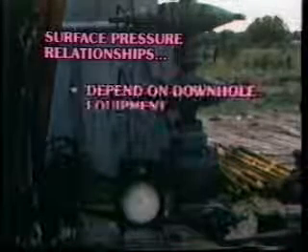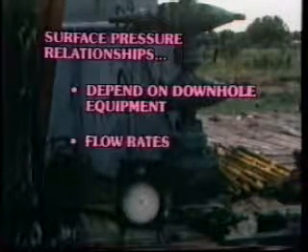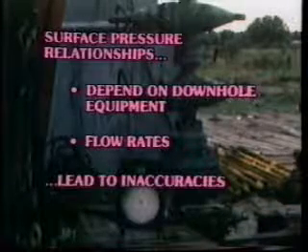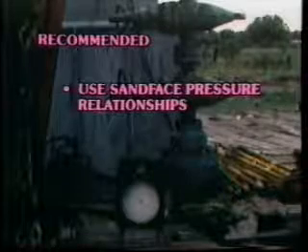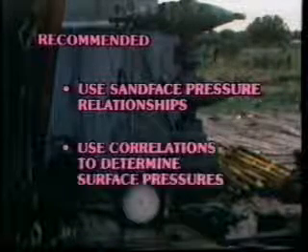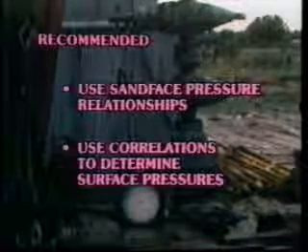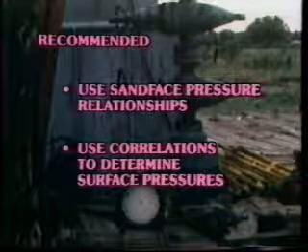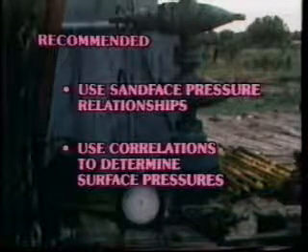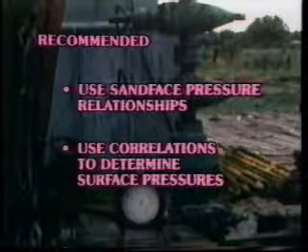However, because the difference in pressure between the surface and sand face depends on downhole equipment and flow rates, a relationship founded on surface pressures will not be constant throughout the life of the well. It is recommended, especially at pressures above 2,000 psia, that the fundamental relationship for the deliverability of a gas well be based on sand face pressures, and that appropriate correlations, usually available in existing computer programs, be used to convert sand face pressures to surface pressures, if surface conditions are needed. Appropriate correlations are given in your manual.